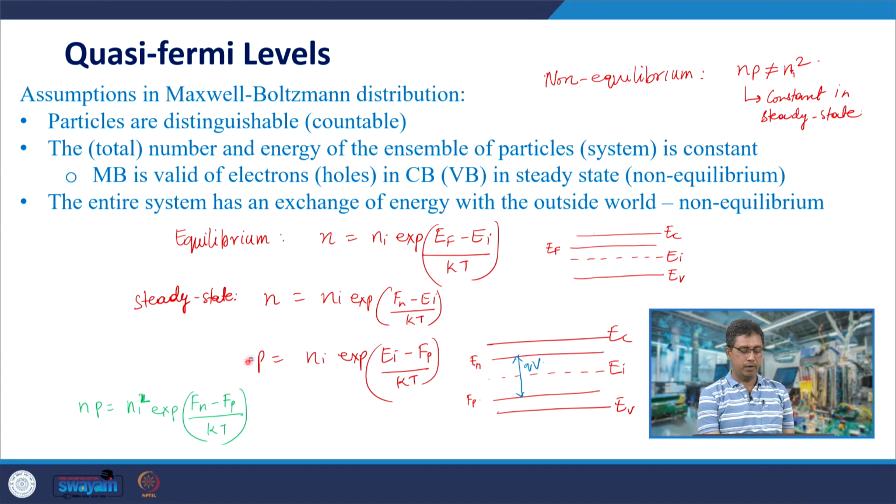Likewise, within the valence band the hole concentration would follow the Maxwell-Boltzmann distribution with the Fermi energy being replaced by a quasi-Fermi energy of holes.